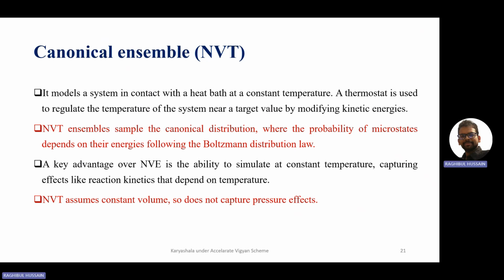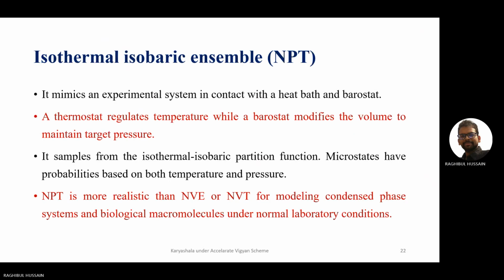So what is the control mechanism I will use here? Okay, thermostat, right. So for the NVT simulation, if your script incorporates the barostat, then just put those values equal to 0. It will be the NVT script. Okay. And for the NPT, you need to keep the pressure within a certain range. You need to keep the temperature within a certain range. That's why you need both the thermostat as well as the barostat.